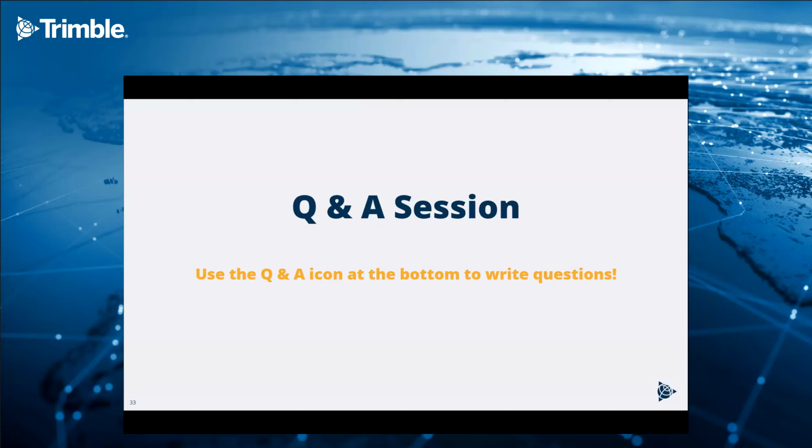What was the other part of the question, Annie? Sorry. Is there a specific converter program that needs to be used? Okay. Well, it really depends on what receiver is being used, and typically the supplier of the drones or the receiver is supposed to give you a converter. In most cases, as far as I know, it's RTKLIB, the RTK library, that's being used to make the conversion from native formats into the RINEX file.